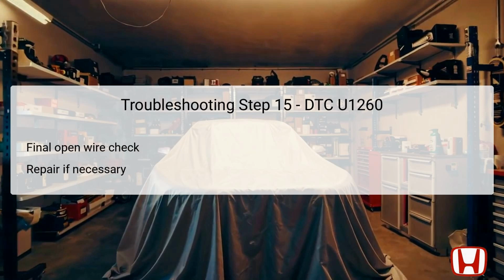In the final troubleshooting step, the focus shifts to assessing the EOPVB, electronic oil pump voltage B line, by measuring the resistance between designated test points. If the resistance reading shows 1.0 ohm or less, it indicates the EOPVB wire is functional. However, a higher reading would confirm an open circuit that must be repaired, specifically focusing on the connections between the auxiliary pump relay and the fluid pump itself.